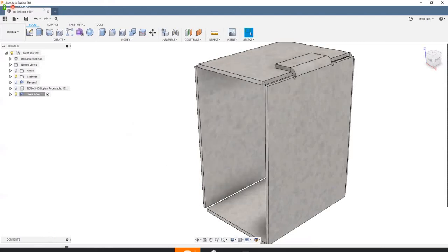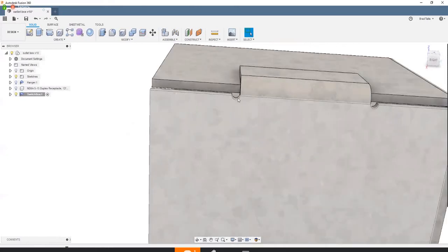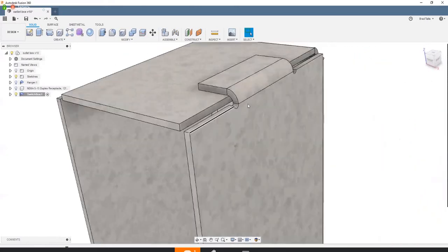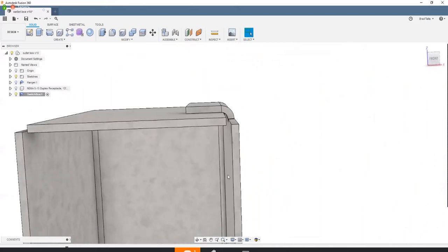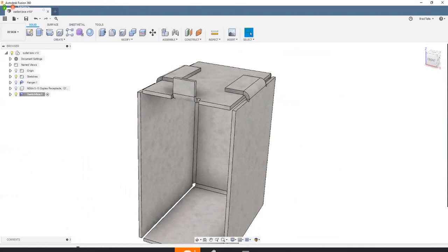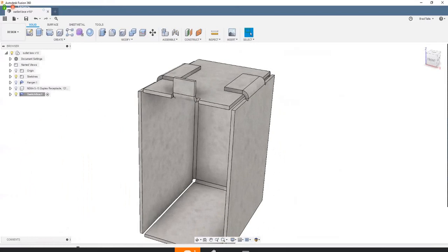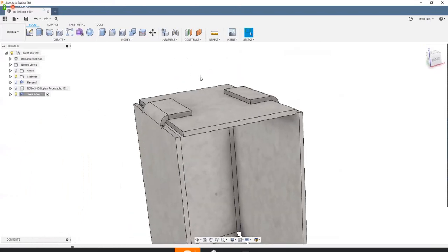Then I just did a symmetric flange, which I was just showing right there. And you can see in this example, in this material, I have a very minimal bend radius, or I'm sorry, relief, I should say. You can see how that flange flips over. And I do that on the top two, I'm sorry. Then we do a symmetrical flange right here. So let's go ahead and see if I can continue on without it dying on me.